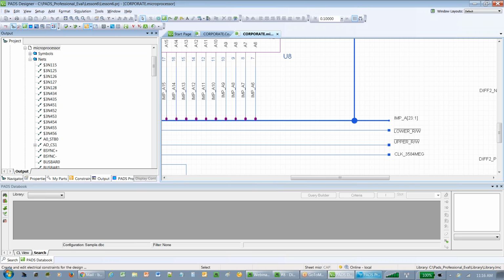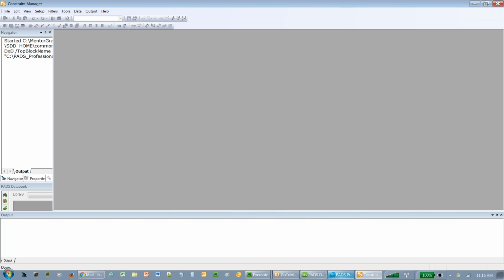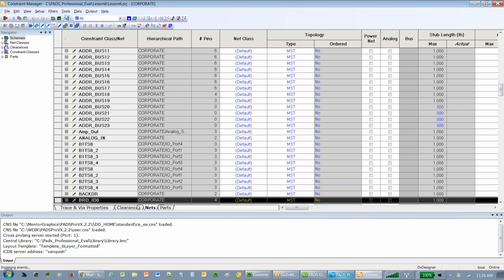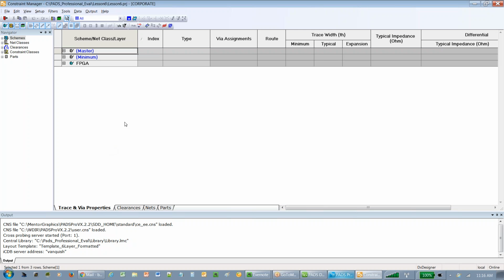All right, but if I open up the Constraint Editor from here, just like I would in the Pads flow I showed a little bit earlier, you have all the same capability. It looks all the same, except we've got an added item here called schemes. This is where, when things get more difficult from a board design perspective, like using a fine pitch BGA or even SOIC or quad flat pack, and you need to specify rules around that part, Expedition and PADS Professional have that capability.